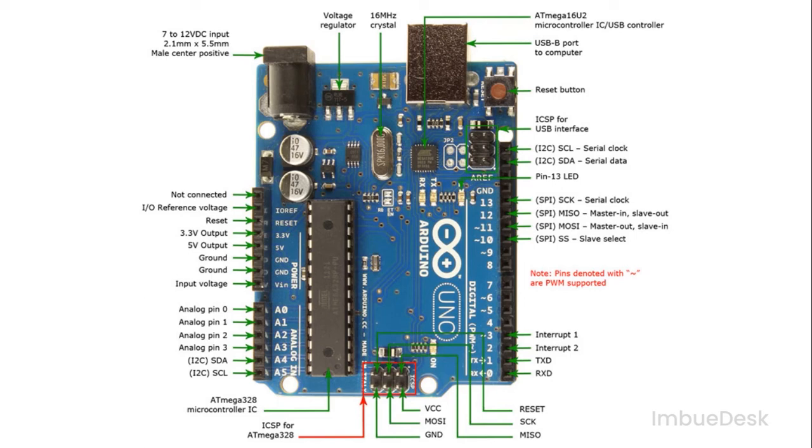You can see two pins which are AREF, that is analog reference voltage, and ground, which are used in designing the voltage part in circuits. There are 13 different digital pins which are used as input-output digital pins that are used to send and or receive data.